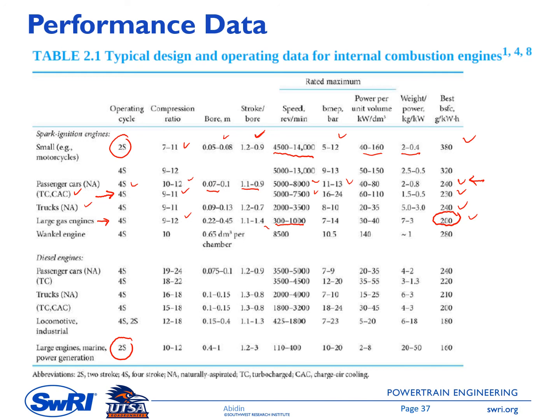Next one is the Wankel engine. This is a rotary engine, so not a reciprocating engine. It has a compression ratio of around 10 to 1. This Wankel engine, as I mentioned in chapter 1, is a compact engine. You can operate it at a very high engine speed, but it has a bad volume to chamber area ratio. Therefore, usually it has a worse efficiency. It has a PSFC of 280 gram per kilowatt hour.